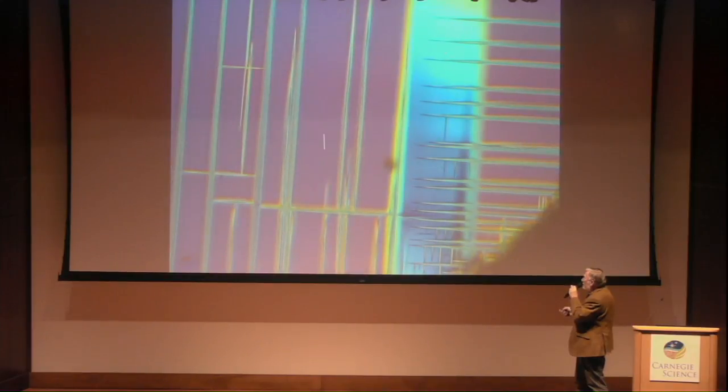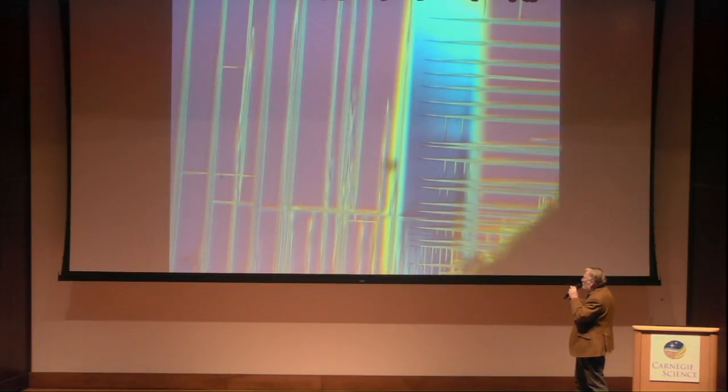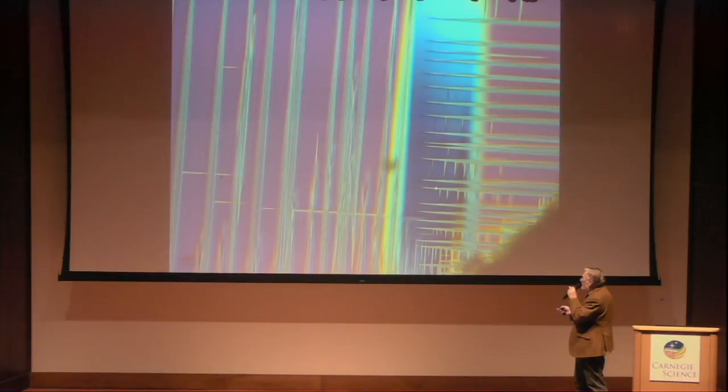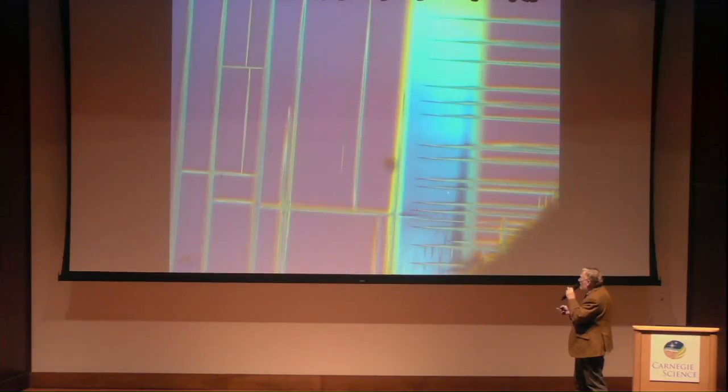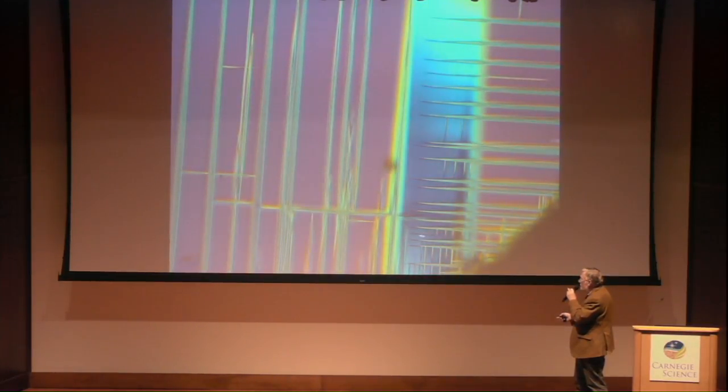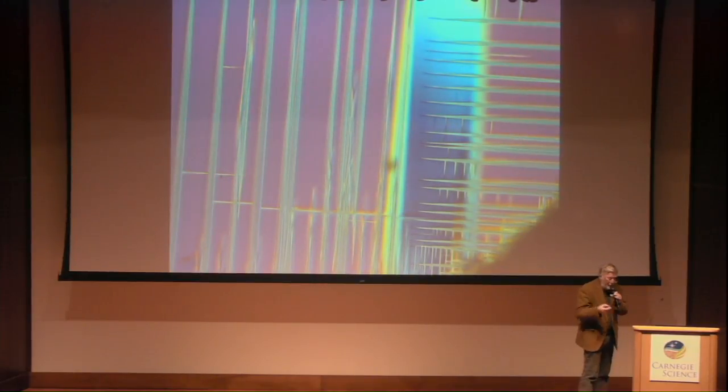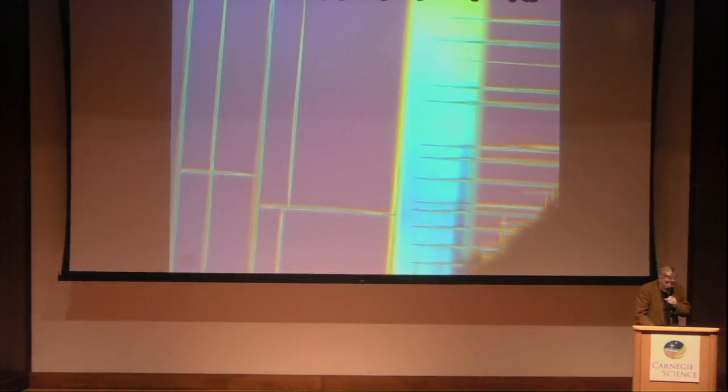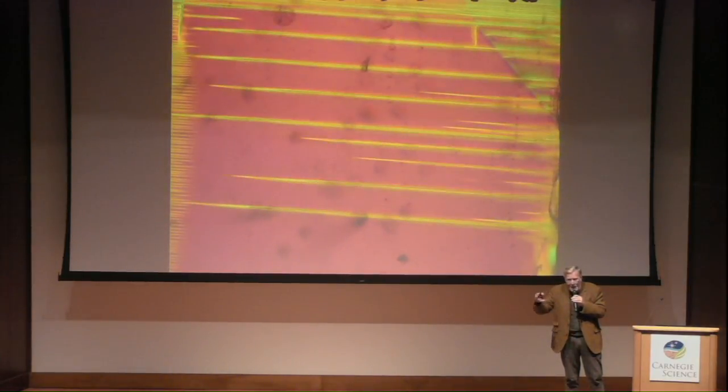Now here is the ferroelastic part, so I squeeze a crystal, I get my primary domain walls or domains, the secondary domains, vertical, then the tertiary ones, and so forth. And if I carry on with that, I go almost to a glass state. And if I rotate the crystal by a little bit, then you can see it's the same crystal, lanthanum aluminium oxide. You can see that this behavior now is very angular dependent, so I can actually, in an engineering fashion, make patterns which are characteristic for what I need to do.